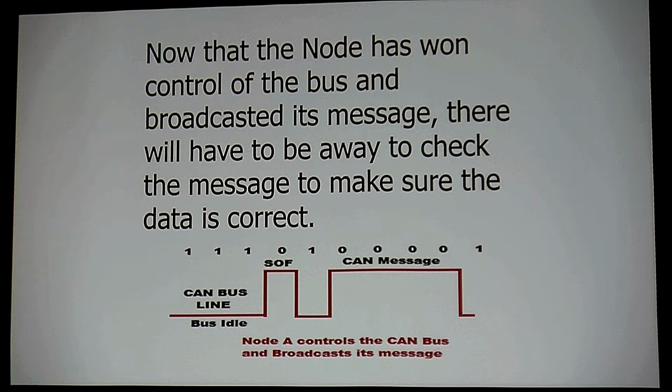So there's always urgencies. And these urgencies mean that I write a special frame that no matter what, it will be broadcast. Every system and every software engineer has these special codes in there for really urgent messages, and they'll take control of the bus no matter what. When I say no matter what, I've got to end the frame that's talking right now. Whoever had control of the bus, he's got to end it. Now the very next one, with the right priority, I win the bus, so I now can control the latency on really urgent messages, but I don't know what my latency is going to be in normal communications.